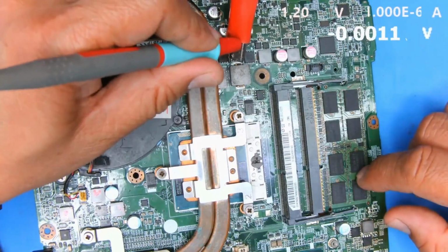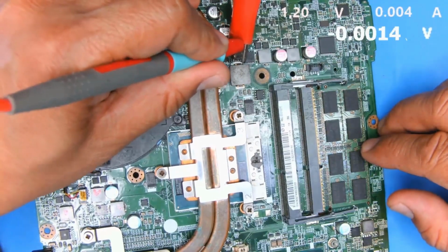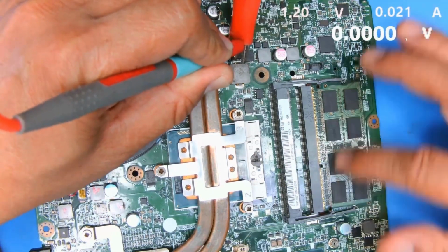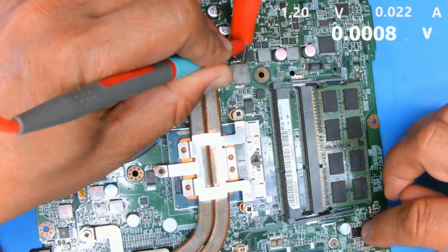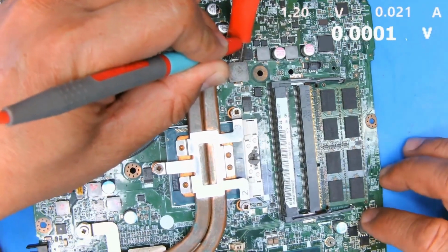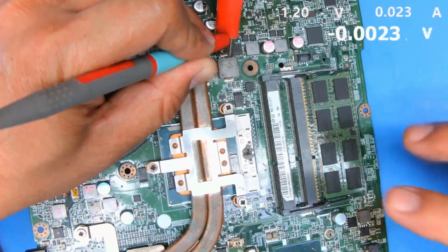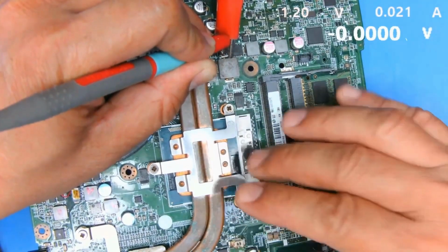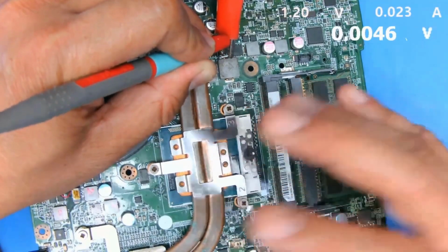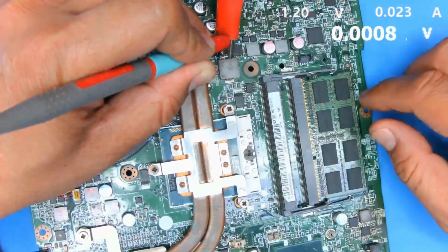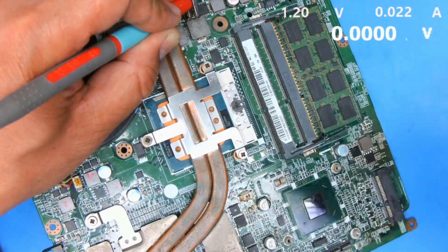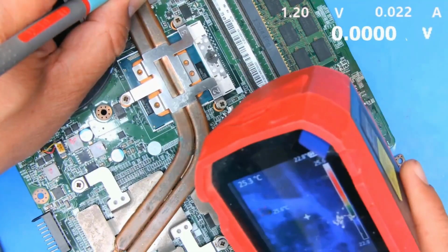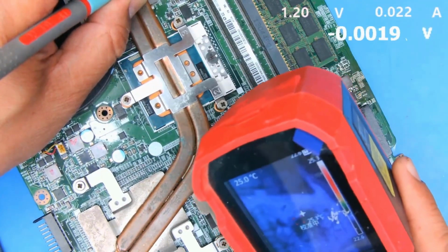So when we supply power, the current will increase a little bit, like here, it's 0.022 amps because there's a load and the power is going into the load. The load completes the circuit. The circuit I mentioned, you need to have a load connected to it. Only then will you find the part that gets hot. For example, if there's a short at the CPU and we remove the CPU, like this, for the machine, you can remove the CPU. If you take the CPU out, the short circuit disappears. There just needs to be a load, that's all, for it to work. The heat only increases a little, but not much. 25 degrees, we probably won't see that.